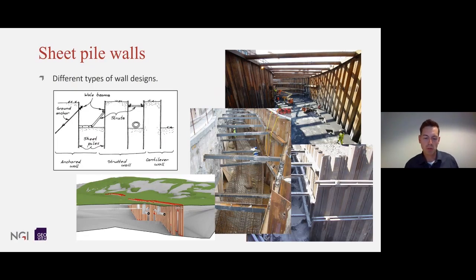I assume that most of the audience are familiar with sheet pile walls, or at least have seen some of them at some point in their profession. So I'll therefore not go into details about that, but I figure that a short intro could be good and useful before we begin the actual modeling. In Norway, it's quite common practice to drive sheet pile walls all the way to the bedrock. And in some cases where we have big depths to the bedrock surface, we'll design it as a cantilever wall. And in some cases, we do a mix of the above.